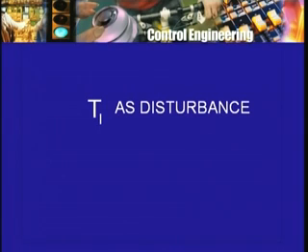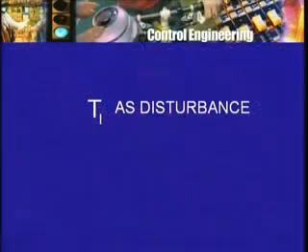In both the equations, the only quantities that appear are the two quantities Ia and omega m, whose derivatives appear, and the other two quantities Ea and TL. TL is the load part of it. Now this is what can be thought of as a disturbance, in the sense that TL may change suddenly in some unknown way. If you know what TL is going to be, then that's one thing. But suppose something happens and the load torque changes suddenly. So TL will be our disturbance variable.